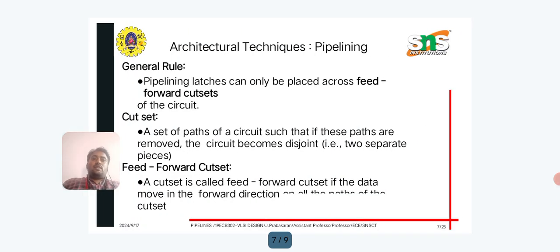Okay, and what is the general rule of pipelining? Pipelining latches can only be placed across a feed-forward cut set of the circuit. A cut set means a set of paths of a circuit such that if these paths are removed, the circuit becomes disjoint. A feed-forward cut set means a cut set is called feed-forward if data moves in the forward direction on all the paths of the cut set.